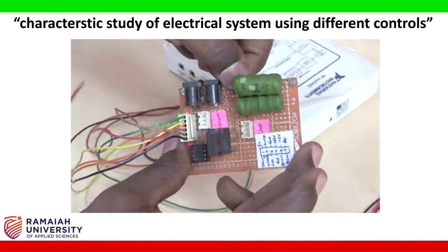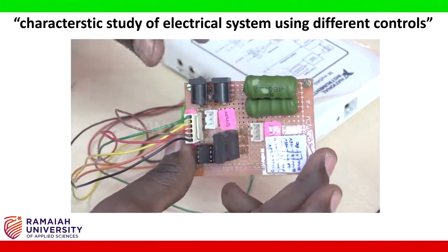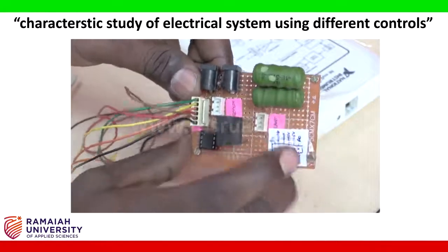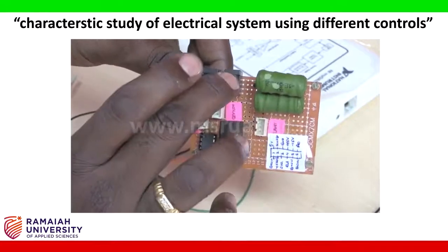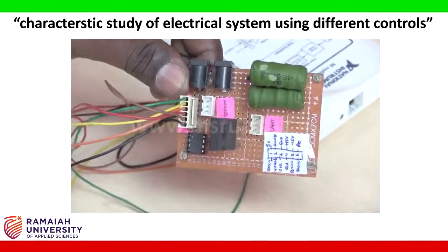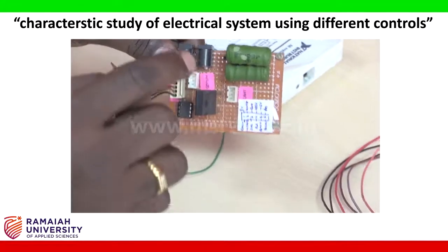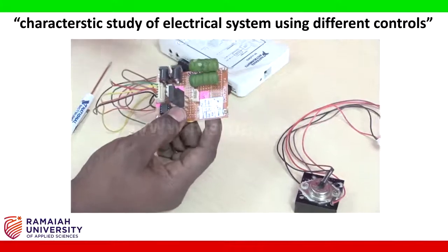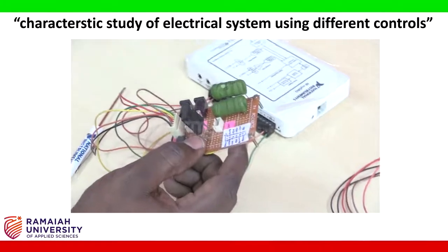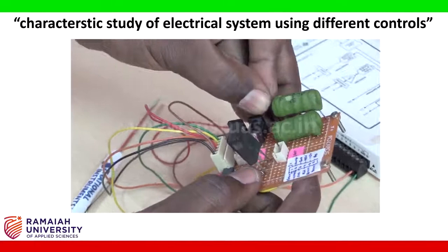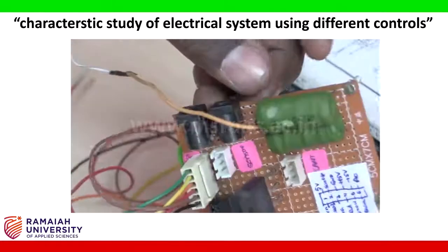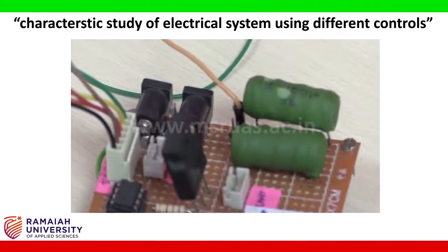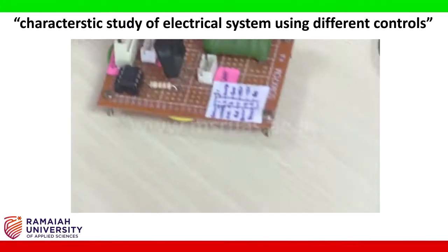Either by using adapters you can power this board, where the 15 volts required to provide a voltage source to the transistors can come through these two terminals, or by connecting a DC regulator power supply to the other terminal at this point you can also provide a voltage source to the transistor.